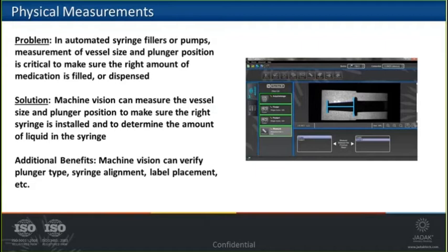Better than that? Well, that's a complicated question, because plus or minus 1 milliliter really depends on the size of the vessel and the container. As you take a milliliter out, how much does that change the level that we see? So we usually talk in terms of distance, say plus or minus a millimeter or plus or minus half a millimeter. Then you use that to back into how much level change you see in linear distance as you remove a milliliter of liquid.